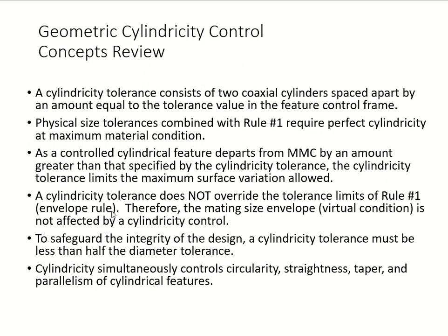Rule 1 is called your envelope rule. The mating size envelope is not affected by your cylindricity control. So to make sure everything is okay in our design, your cylindricity tolerance has got to be less than half your diameter tolerance. Okay.